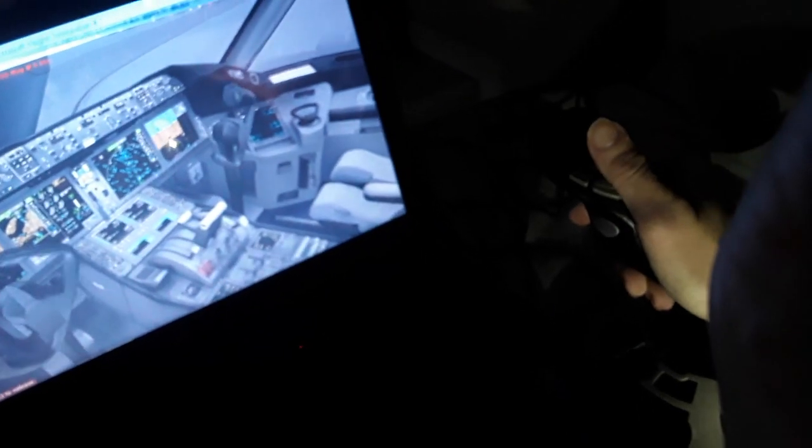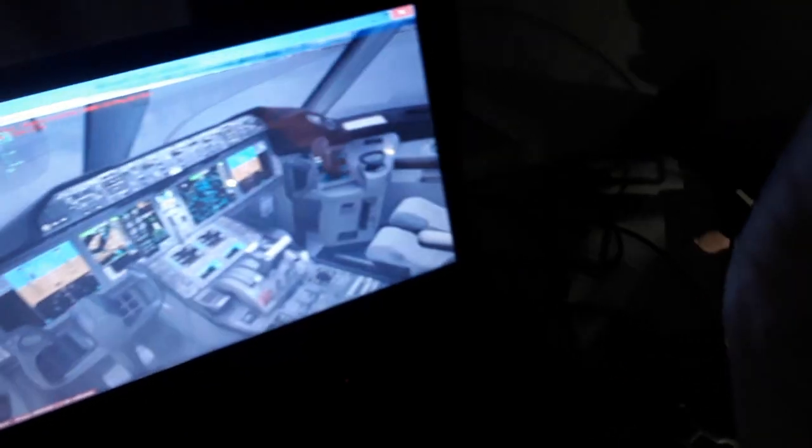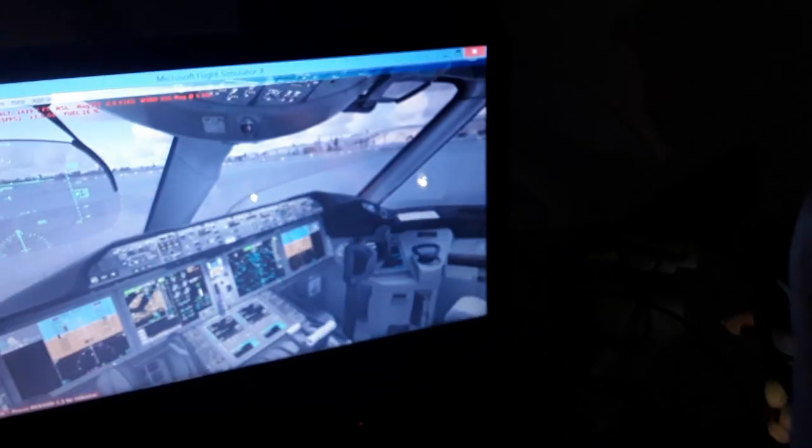In normal mode, in the Airbus, we can make left and right turns, 67 degrees with full stick deflection, or 33 degrees if we leave the stick off. This accounts for 2.8 g, where 1 g is the acceleration of gravity, in left and right turns, limited by the flight control computers. Also we can climb 30 degrees and 1.5 g, or we can descend 15 degrees or minus half g in the Airbus aircraft. Also we have the alpha protection and the angle of 1g stall and other protections, speed protections. So we have also similar things in the Boeing aircraft.